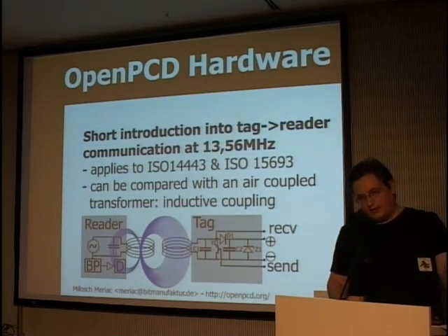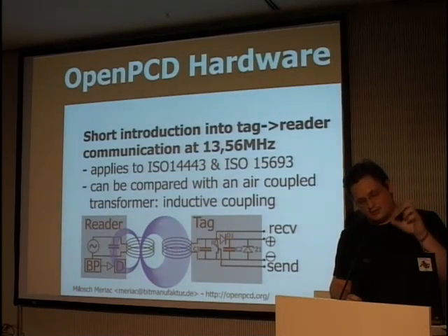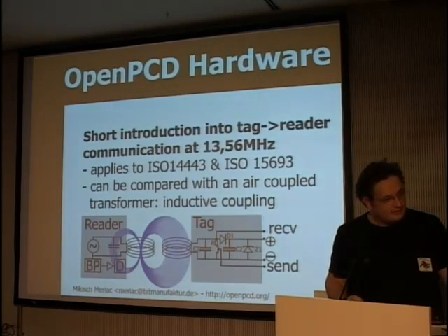You have basically a diode that is meant to demodulate the carrier and to remove the carrier frequency, and a Zener diode to clip high voltages. And the back channel is by applying a resistor to the input RF interface.